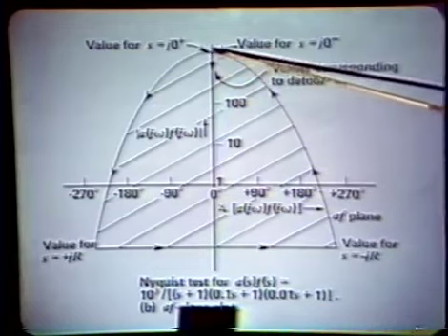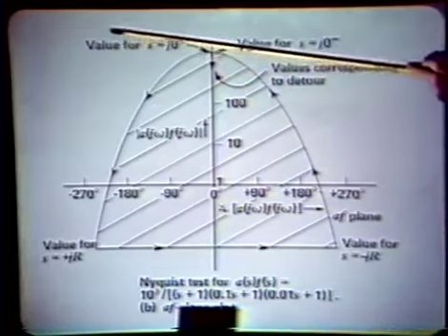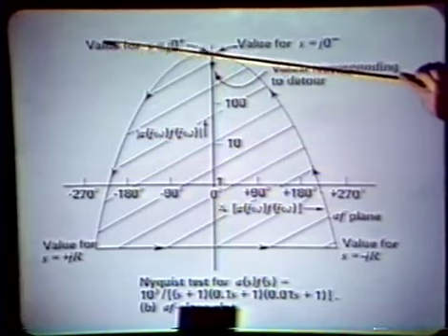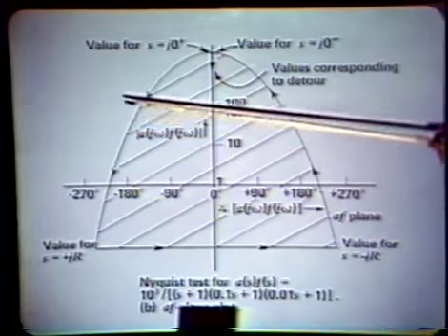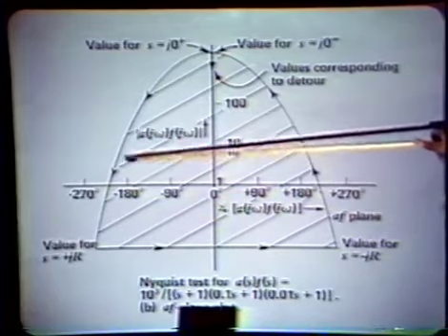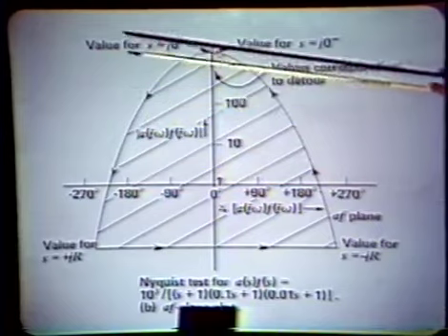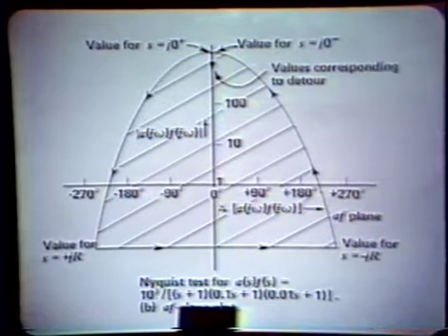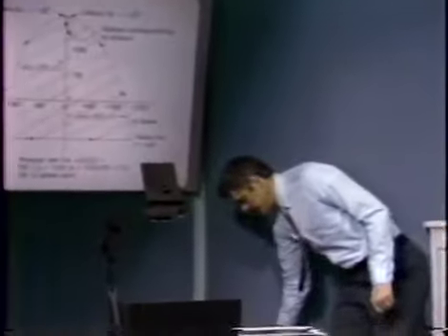If we lowered the A0, F0 product, that would correspond to simply sliding the shaded curve downward. If we lowered it enough, we'd finally get it down when we lowered it about this much. We'd finally get the curve down to the point where the -1s were outside the contour. Then the system would be stable. And that corresponds to the condition